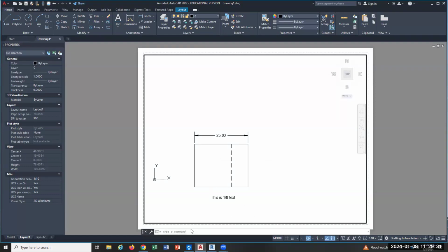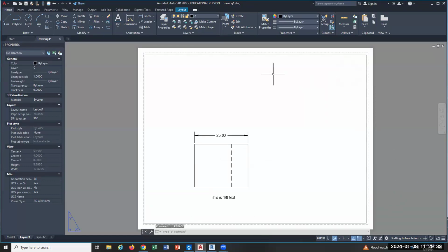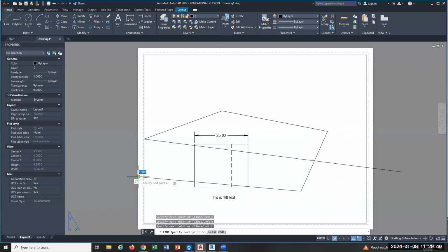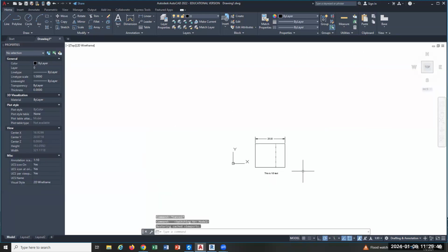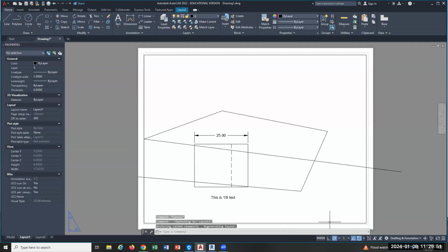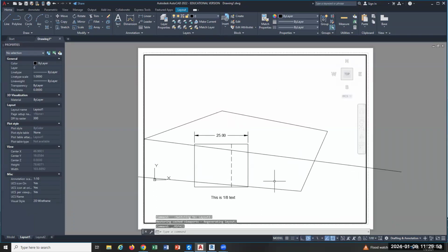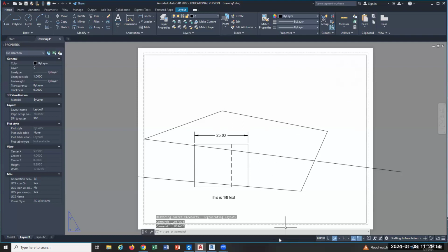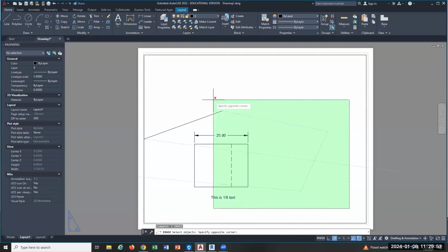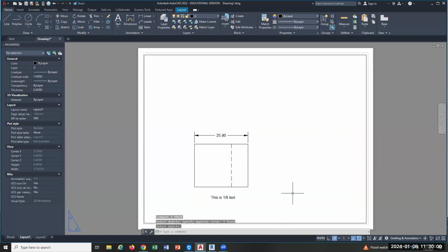You have a title block to build. That should be in paper space. This is paper space. So when I draw lines in here in paper space, remember, it's just on this piece of paper on top. It doesn't affect the model at all. So there's paper space and there's model space. If I drew now, it would affect it. So you jump back and forth. So I'll erase this. But that's where your title block is going to go, right? In paper space.